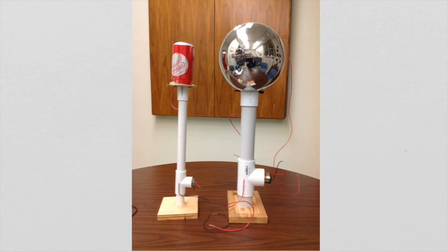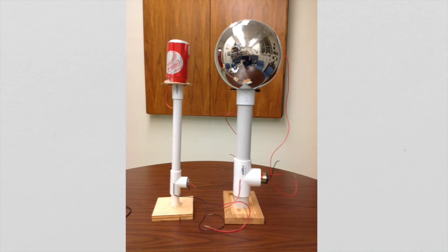So a sphere of 5 centimeters in diameter would be approximately the same size as the Coke can, but the Coke can, of course, will not get anywhere near 150,000 volts before dielectric breakdown because of the high curvature along the edges of the Coke can. But the voltage on the Coke can should easily get up to 10,000 volts.